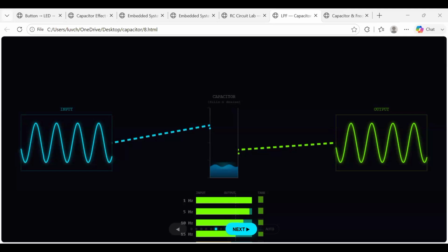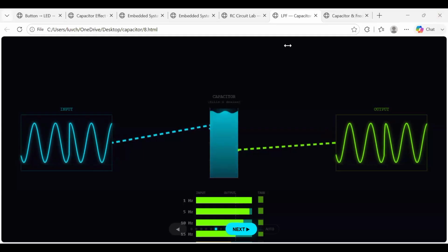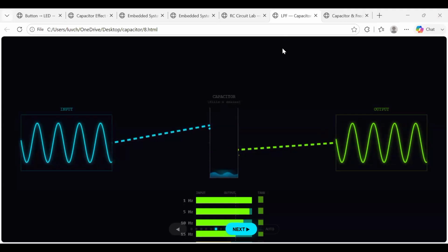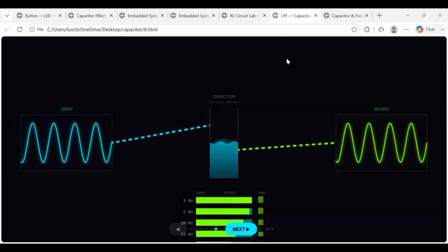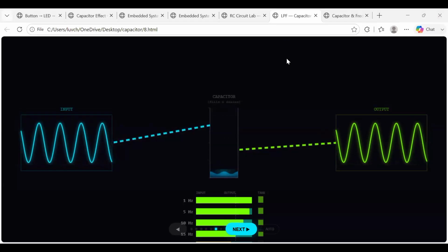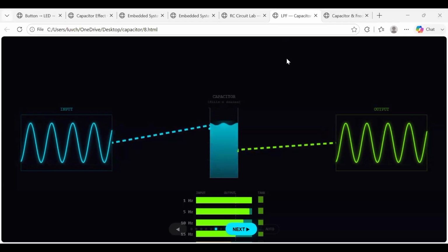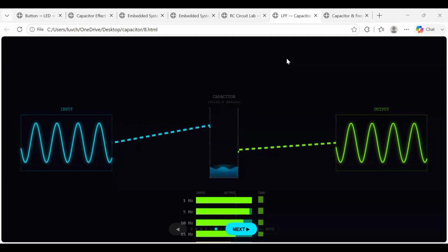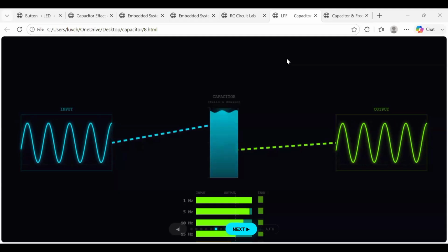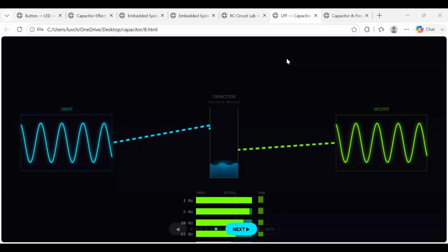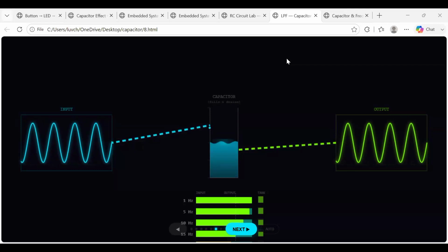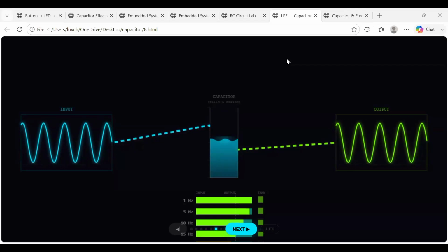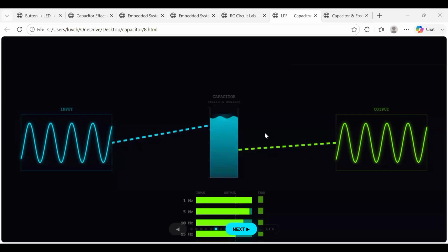I want you people to understand the value of R and C is designed by the amount of time taken by the button. Let's say the button is replaced with a joystick. Then you have to design the R and C value depending upon the time taken by the joystick, right? So this is how questions will be asked in your interview. They never try to ask a question from your theory perspective.